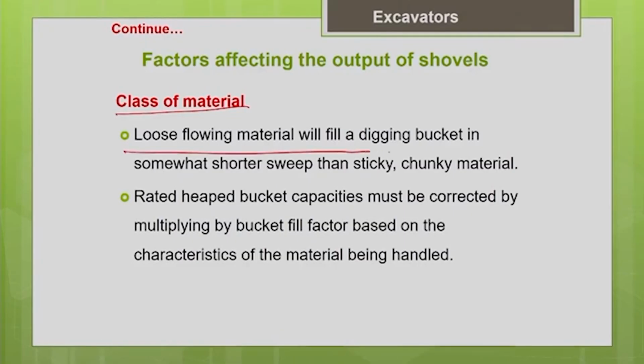But if it is going to be a sticky material or rock or chunky material, in that case it may take more time to load the bucket. So it depends upon the flowing ability of the material. So that is going to affect the cycle time and the productivity of your machine. Loose flowing material will fill the digging bucket in somewhat shorter sweep than sticky and chunky material.